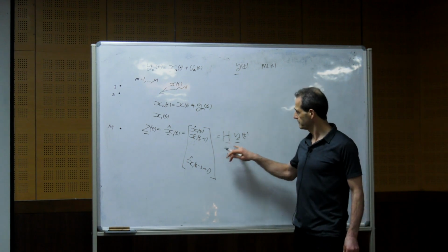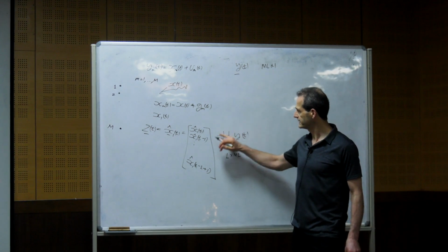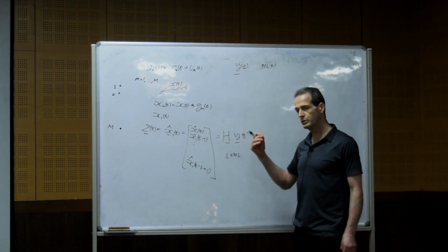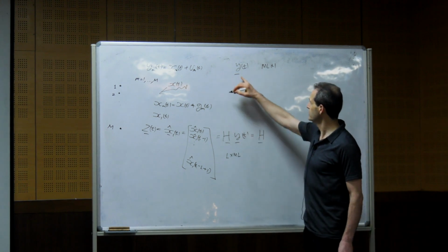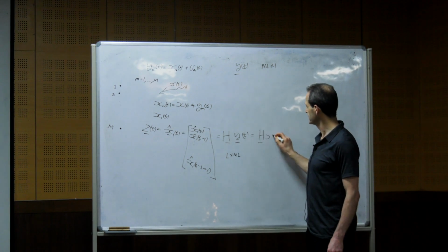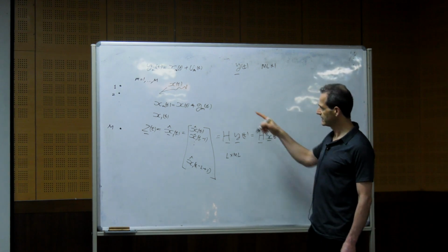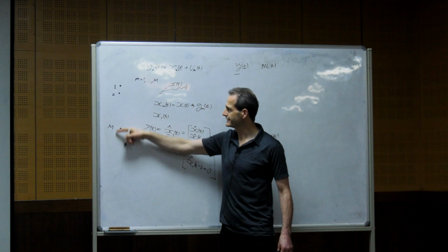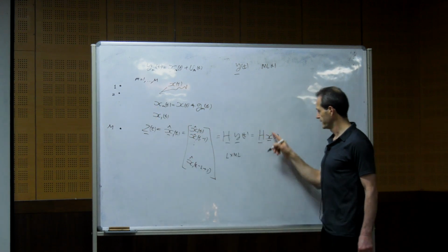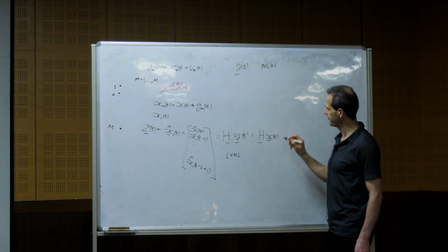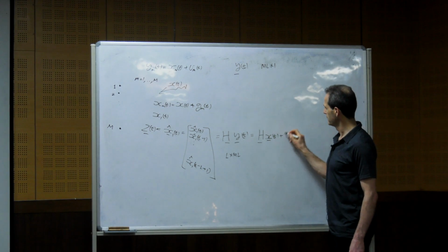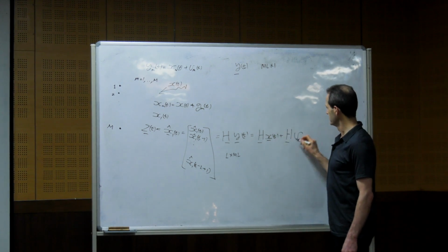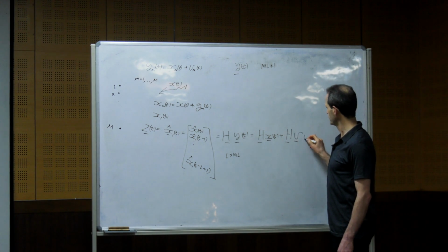So the mean squared error means, you see that when you estimate something like that, we have two components. Because also here, this vector y(t), we can write it as a summation of two vectors. This is the desired signal that is measured in all the sensors, L samples concatenated over all the M sensors, so we have ML samples of x plus ML samples of the noise.